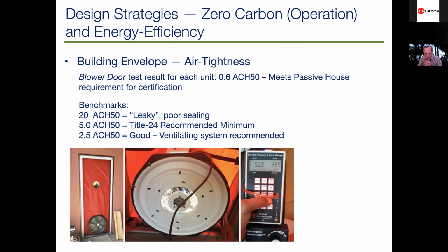And so the developer had a devil of a time sealing each level because the wall panels were too perfect in their way, and the construction of the floor was still relatively uneven and uncontrolled. But they went around and sealed and found every spot that was leaking, and finally it passed the test. So that was kind of a lesson learned, but they did get the airtightness they wanted.